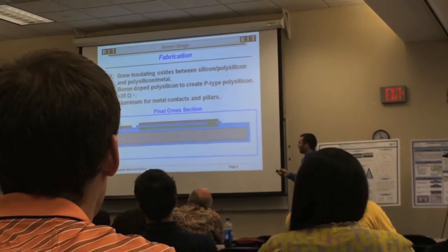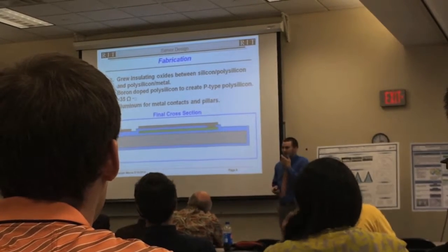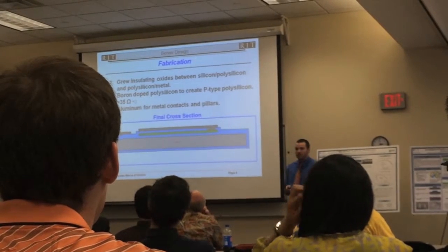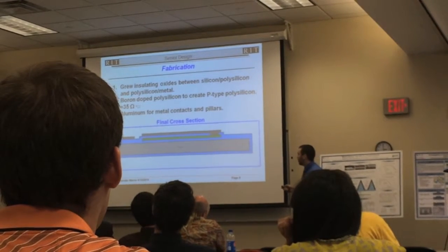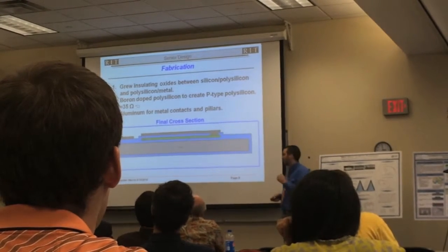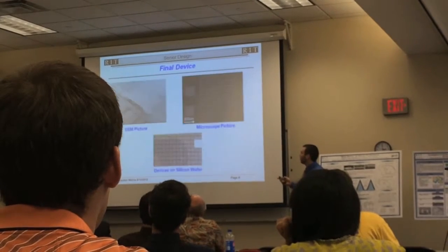Etched through the oxide for the contact cut, and then deposited the metal and etched that away to define the device. And also did a sinter process in case there's any native oxide here to make sure that resistance was low and there were no open circuits.